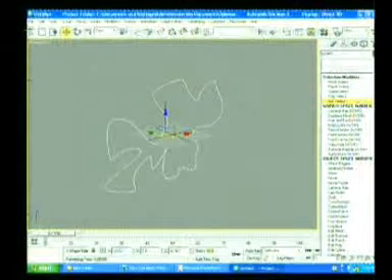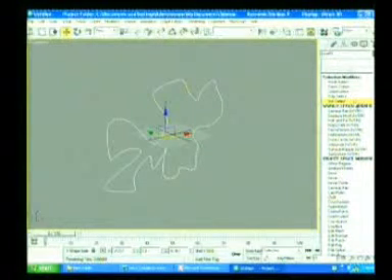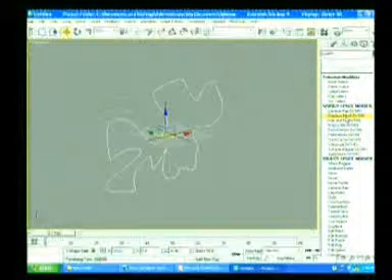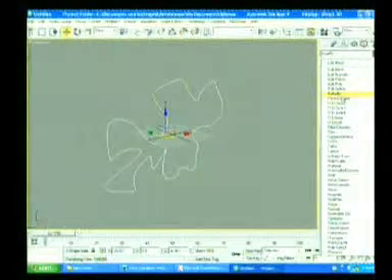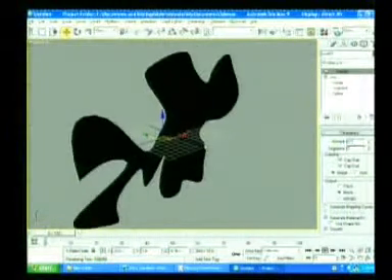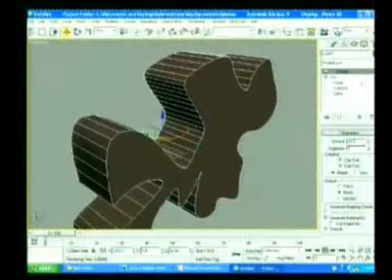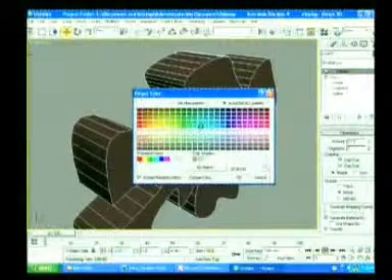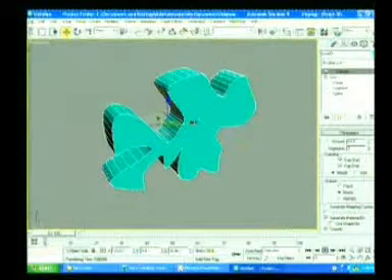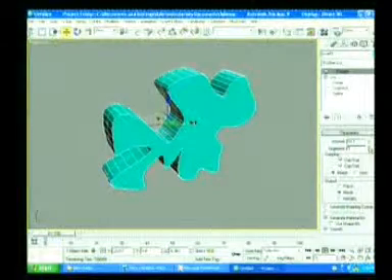You put extrude on this line or spline to fill the space of the shape. Press E for extrude. It's going to be filled, and then how much amount I want to extrude this. Here is the amount, and again here are the segments.